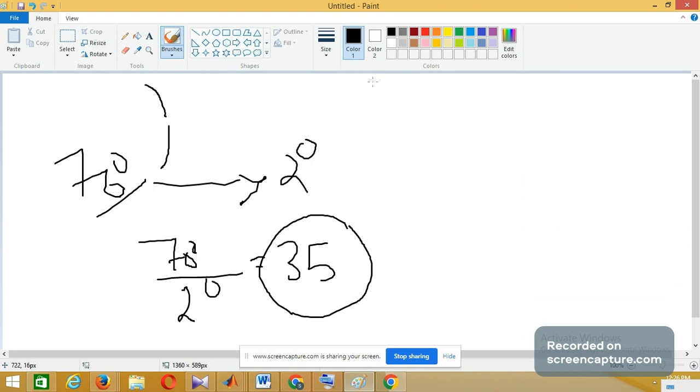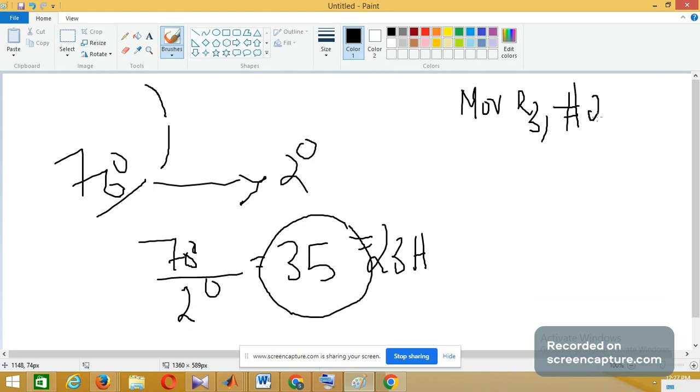So let us take an example. Let us take this program. So you know that 35 converted to hex, in a calculator, the corresponding hex number is 23H. So this 23H is kept as a counter in some register, R3. R1 and R2 I will use for delay. That's fine. So in R3 I will keep 23H to say that we want 35 times.